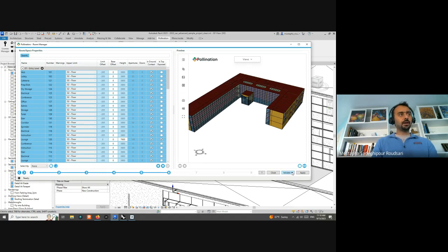The other things that we have here, you can validate your model. You can validate the whole model, and you can also check room overlaps. This is my favorite one, because if you have rooms that overlap, and it happens in Revit a lot of time, and you don't check them, when you go to IESVE, you get this error that rooms are intersecting, and you have to come back in Revit and fix them. This model doesn't have any issues, but if you have any room overlap issue, it lets you just zoom into that room and fix it inside Revit.